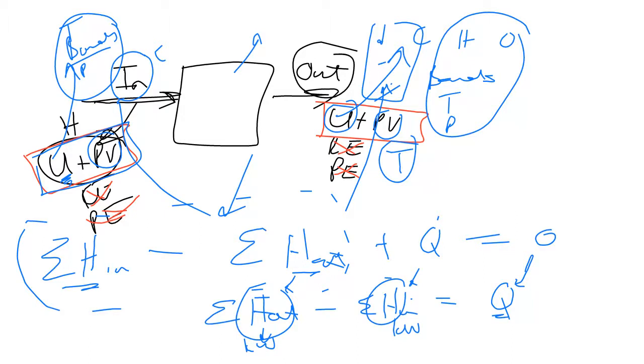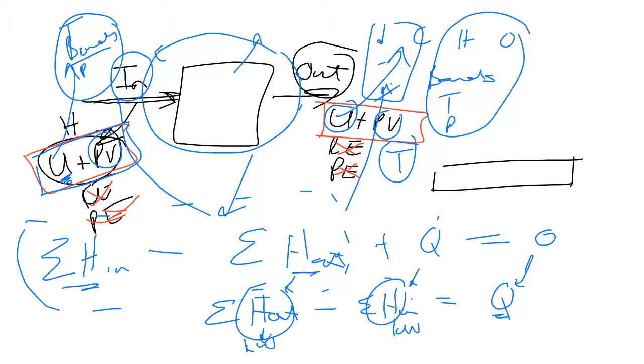So the way we account for it in this course, because we are not only interested in the overall energy balance, unfortunately, or fortunately, because we can have fun with it. We are interested, specifically in a plug flow reactor, in what happens here in the middle. We need to have a temperature profile along the length of our reactors. Why? Because the temperature seriously affects our rate.